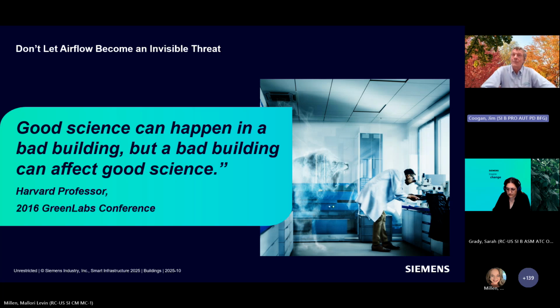How does contaminant sensing make sense? If you can still detect that the people are in the lab doing their work, and if you can detect that something's coming off. Maybe the most important chemical is not sensed, but something's coming off and we're picking it up and we're saying, hey, they're doing their stuff in here. Let's adjust the ventilation. That's frequently the line of thought that justifies a contaminant sensing approach.